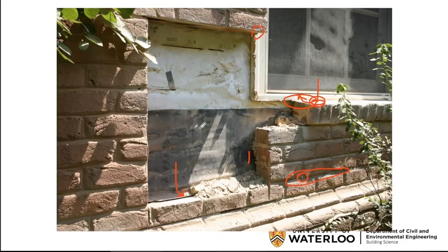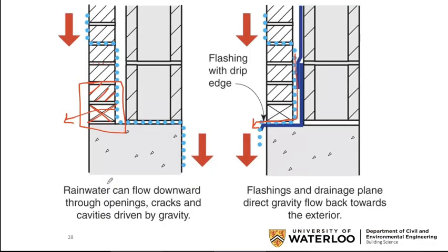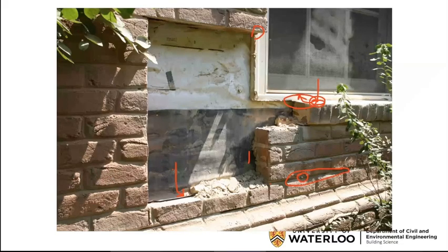So this nylon rope blocks water from leaking out. And so it really didn't have any drainage outlet. The flashing didn't go all the way, and the weep hole wasn't actually there. So I think, Marley, this part actually is one of the big problems. It didn't go far enough, and it also doesn't have weep holes. But there's something that is more fundamental than all of that, which is what really caused this building problems.